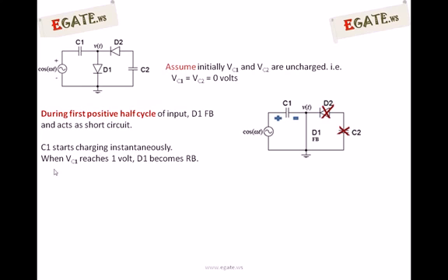This current flow path includes cos omega t, C1 and diode 1. Cos omega t doesn't have any resistance, C1 is ideal, D1 is ideal. So in the total current path, it doesn't find any resistance. So tau is equal to R into C, where R is 0, which makes tau equal to 0. Tau equal to 0 means the capacitor charges instantaneously. Whenever you apply any voltage, it is taken by the capacitor at that time itself. So capacitor 1 charges instantaneously.